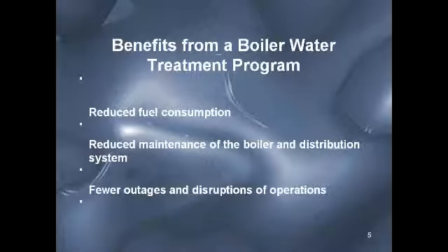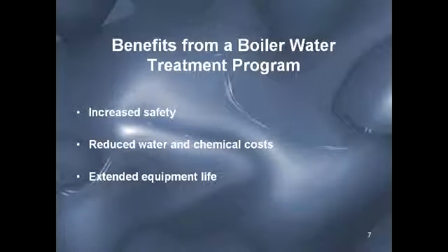To inhibit corrosion in boilers and their connecting steam and water systems, to inhibit stress corrosion cracking, and finally to maintain high steam purity by control of boiler water carryover. The use of a proper boiler water treatment program will benefit the cleaner by reducing fuel consumption, reducing maintenance of the boiler and the distribution system, having fewer outages and disruptions of operations, also by increasing safety, reducing water and chemical costs, and extending equipment life.